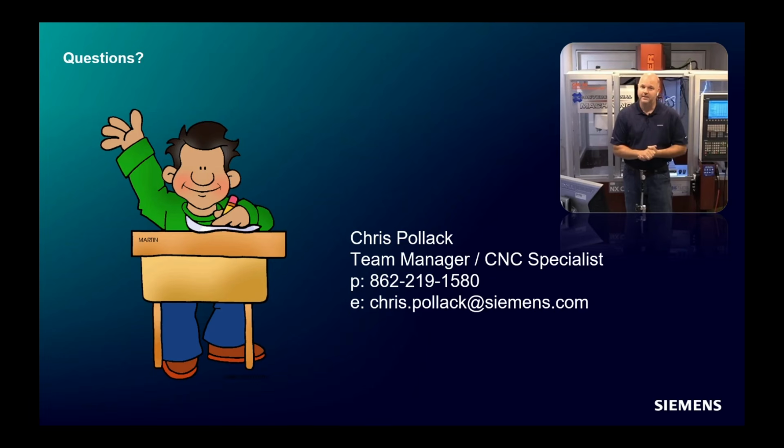What is the main feature of using Cycle 800? What is the difference between other cycles and functionality? I think you touched on this in your first couple of slides, where you showed the animation between Cycle 800 and how it tracks that zero. I think that is really key. To Traore, absolutely. I would say Cycle 800 and Traore are very, very similar. Cycle 800 during the rotary motion is not dynamic, it's static. So I have to send the machine to a safe retract, drive it to position, and then come back. Traore is a true dynamic transformation where it'll rotate with it.